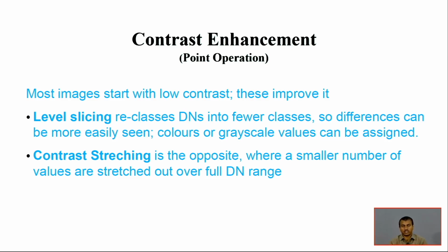In the remote sensing regime I am talking about, the brightness value describes the surface features, the surface brightness, about different characteristics. It may be vegetation, land, a roof surface, a road, like that. So, this DN, digital number, is nothing but the brightness value. If it is an 8-bit image, in the gray scale regime, it is 0 to 255. And if it is 11-bit, the range will increase much more.